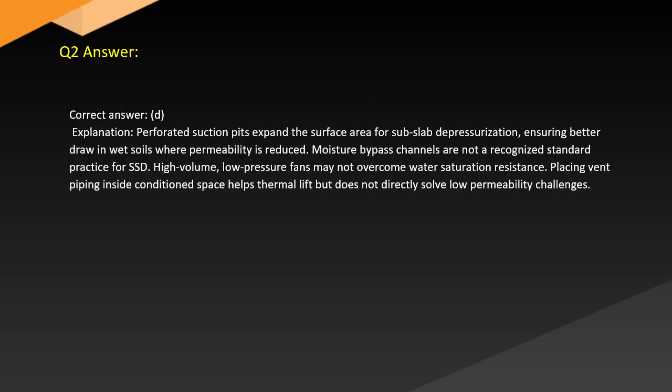Answer. Correct answer: D. Explanation. Perforated suction pits expand the surface area for sub-slab depressurization, ensuring better draw in wet soils where permeability is reduced.